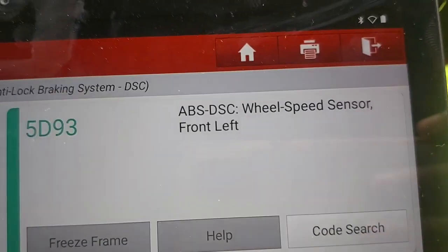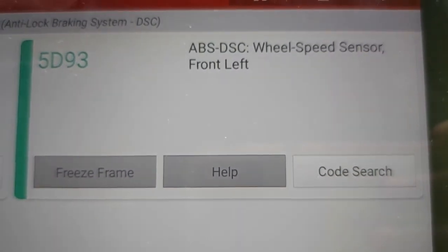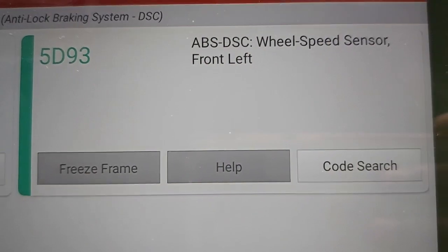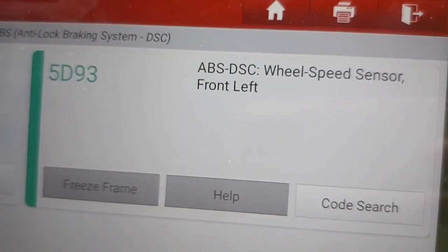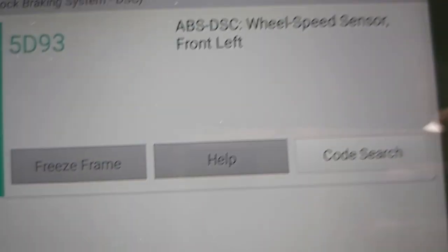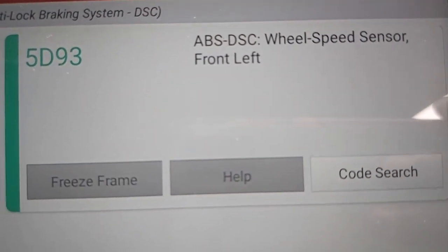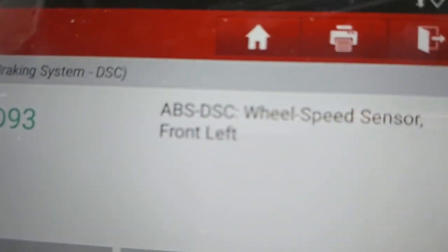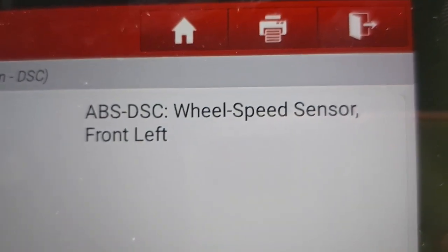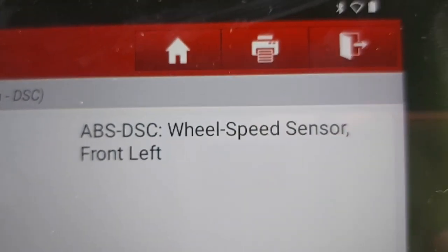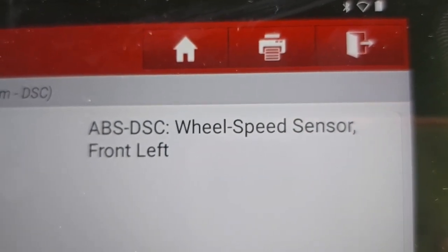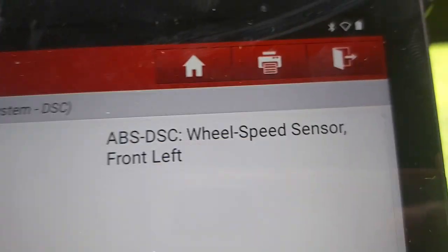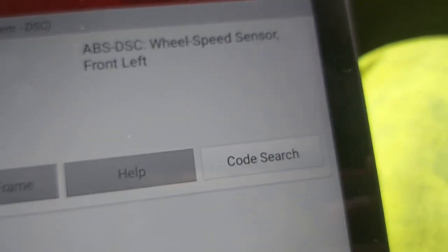I'll tell you the reason why I've decided to start there. Well, it's a matter of checking the vehicle up and checking if my sensor is secure. But besides that, I changed the coil springs, both sides. So I'm just thinking, did I do something naughty there? I don't remember disconnecting the sensors, but I know taking them off from the strut where they mount. I didn't disconnect the sensor. So I think that would be my easiest position to start from.